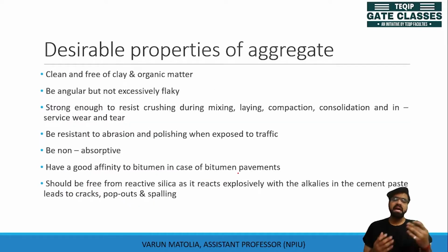Talking about the desirable properties which we want to see in aggregates, aggregates should be free from clay and organic mineral. Why? Because with moisture, the clay and organic mineral tend to change their dimension. The swelling occurs, and this kind of change in dimension is not desirable in your pavement aggregates.